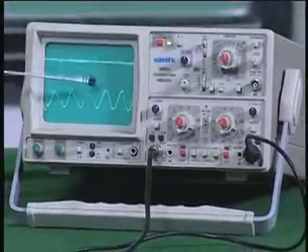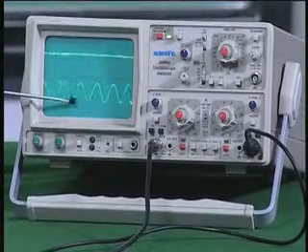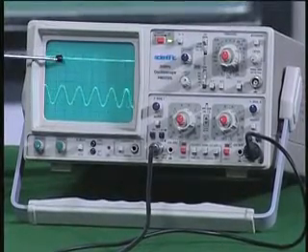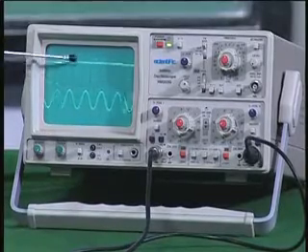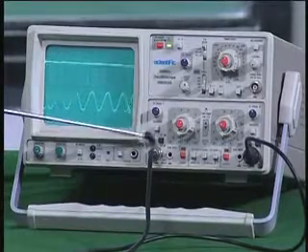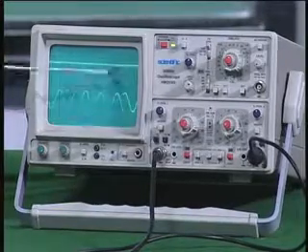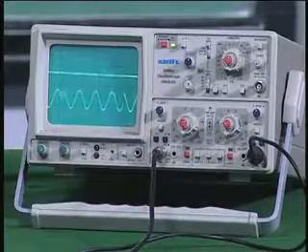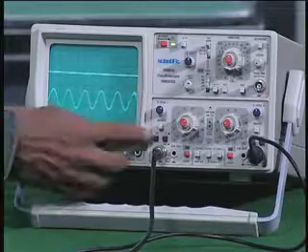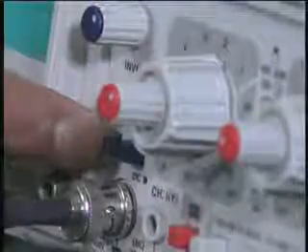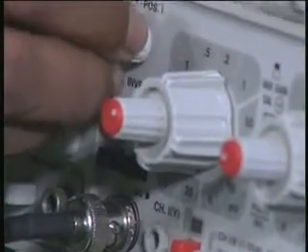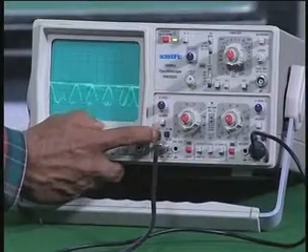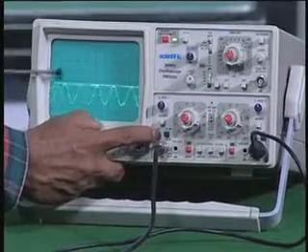On the oscilloscope, this is the input, the sinusoidal wave at the bottom, and the output you see is a DC. It is a straight line, it is a DC. But how much is the DC you can measure by using the DC key here. If I press the AC and the DC key, now it is in DC and now it is here. If I now release that, if I make it into a ground, you can see the signal comes at this point. If I release it, it goes up. So that much is the peak. Now what I will do is I will bring it at the bottom or at the center, and then you can see it is actually going up to the peak value.